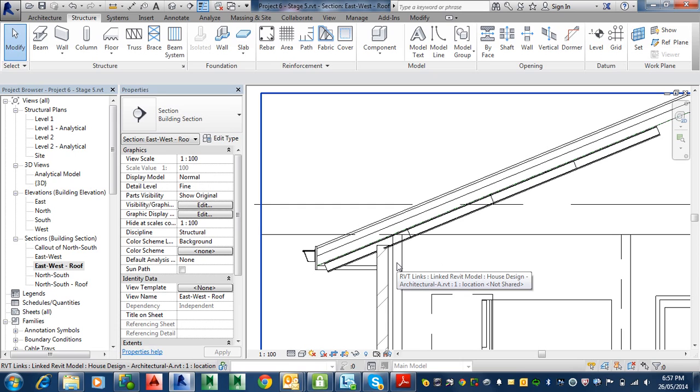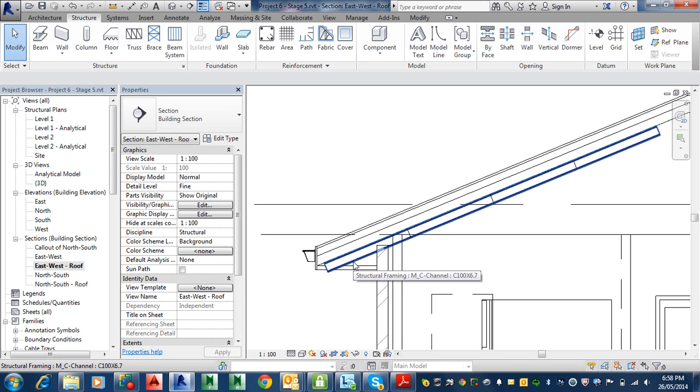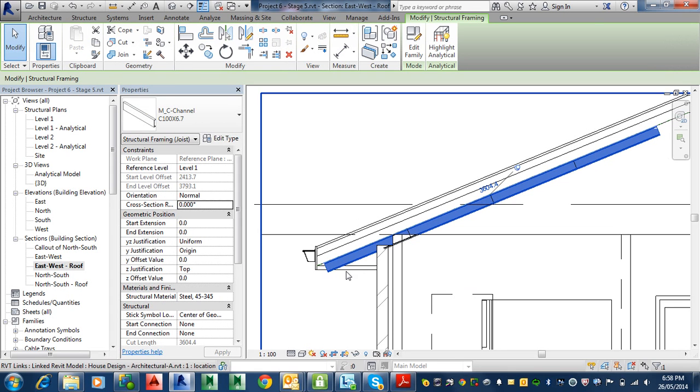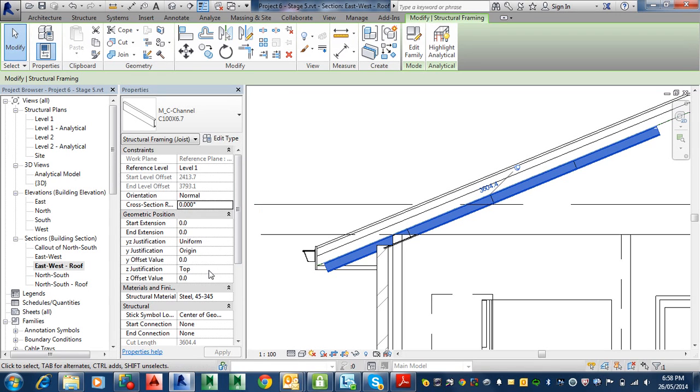So, all right. When you select them, you can actually go on top of that reference line? No, well, it depends how they created the family. That's how it comes in. Yeah, so if it was justification below, underneath here, it would have ended up on top of it, but justification happened to be on top. If I go into another look, I'll probably work it out. There you go, justification is top. I could even maybe change it to, let's just see if it works. This might save us a bit of time. Yeah, that saves us time.